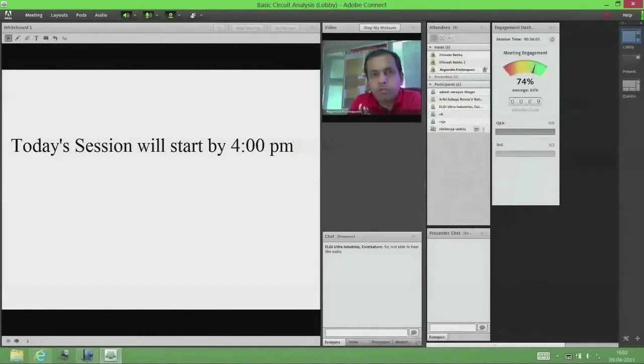Hello and welcome to all of you after a long break. In the previous lecture, we were discussing RC circuits. Before that, we had only considered circuits with resistors, which have no memory. That means that to evaluate what happens with a time varying signal, you just have to calculate point by point. And also, all the equations we got while analyzing resistive circuits were algebraic equations.